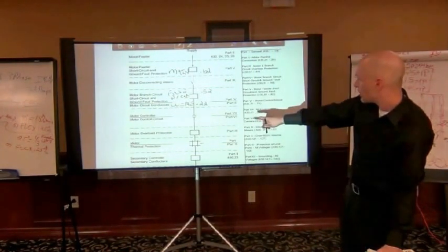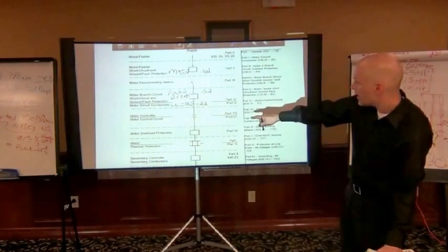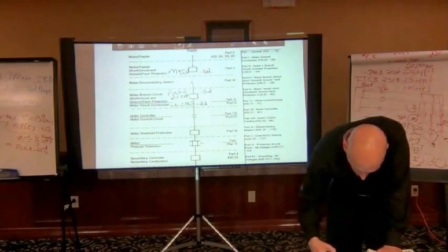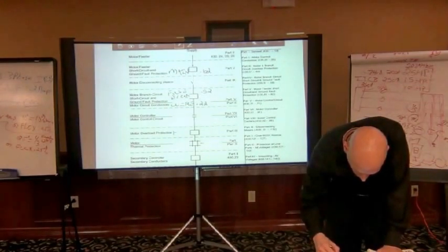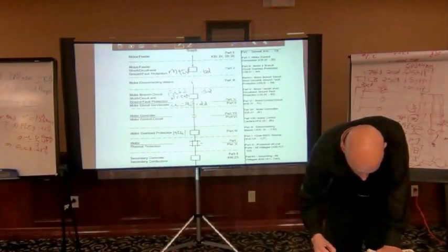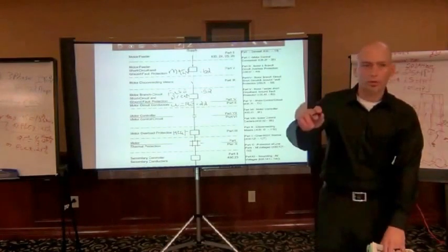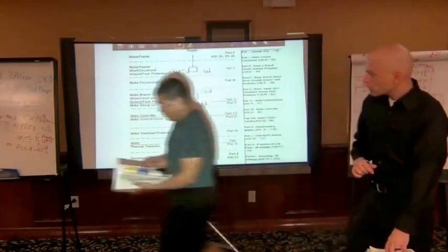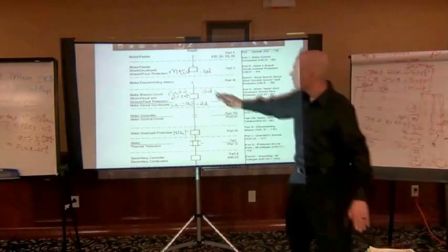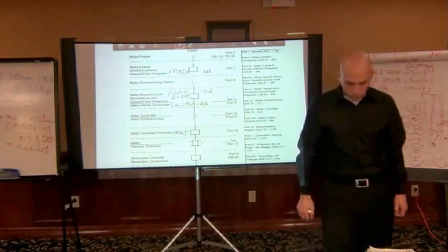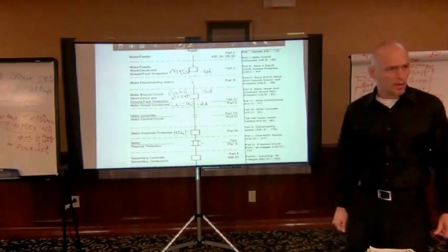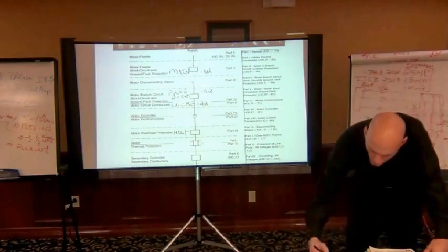And overload protection, under part 3, that's going to be heat, dot 32. So the main, the motor feeder, short circuit, and ground fault protection, or which one? Main, yeah. Main dot 62. Oh, okay, so in that part. Yeah, it's dot 62, it's just your main breaker, main protection. And heat's dot 32.